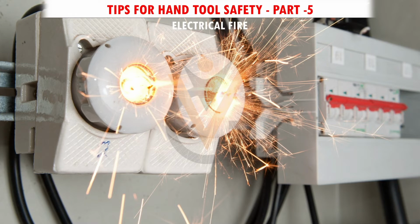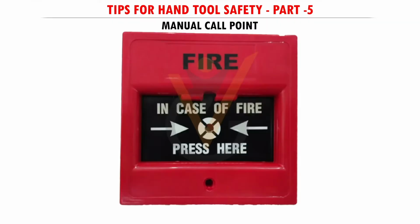Electrical fire. Electrical fires are caused by overloading, faulty or exposed wiring, or when flammable objects are placed near a light bulb. In case of an electrical fire, follow these four steps. Raise the fire alarm. Soon after observing fire, raise the fire alarm by the manual call points nearby.